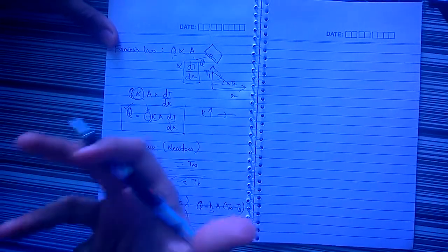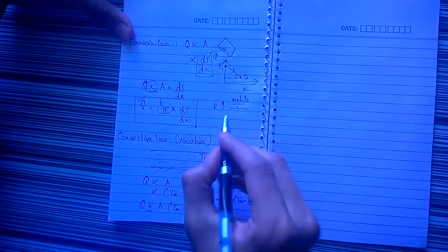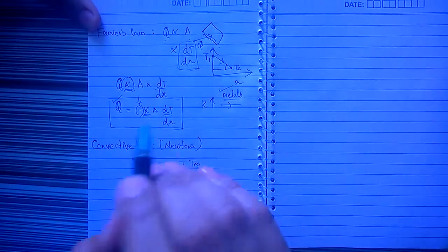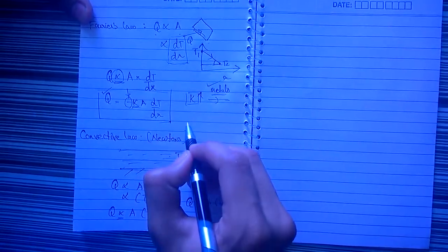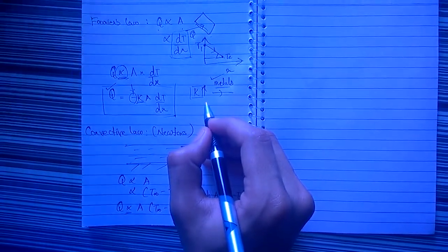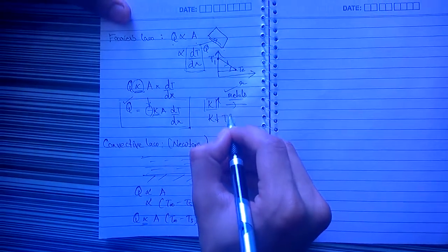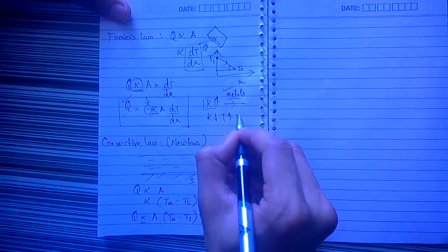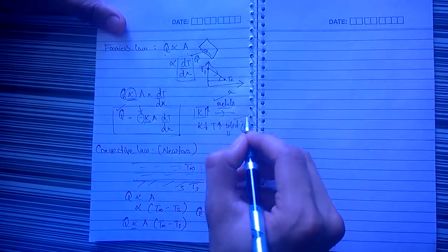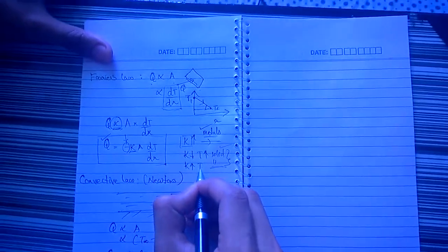Such objects that we observe in our daily life are metals. That is the reason why we use metals for cooking food, because they easily allow the heat to pass through. We find that K as a property behaves differently for solids, liquids and gases. K decreases with increase in temperature for solids as well as for liquids, though there are exceptions in both cases, like aluminium and uranium in the case of solids and water in the case of liquids. But in the case of gases, we find that it increases with the increase in temperature.